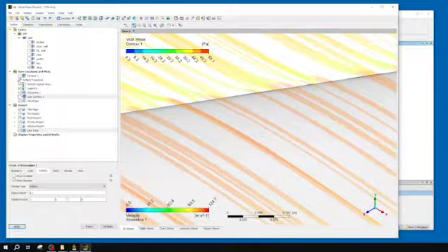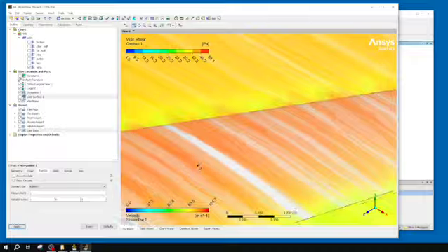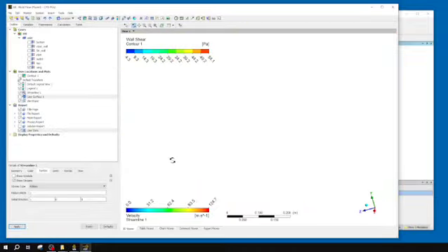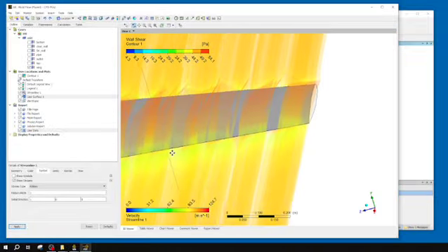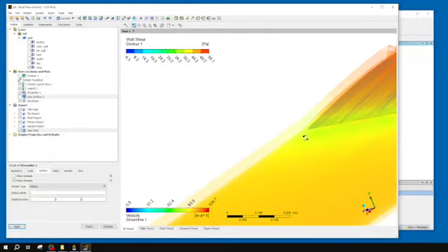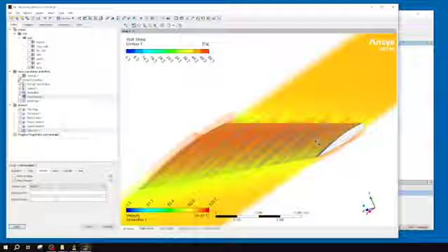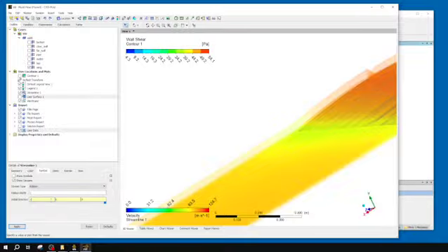But let me give them a 1 scale. How does that look? That's actually quite hard to tell what's going on with 100. But yeah, this initial direction just is a factor to rotate the ribbon. Generally, you probably don't need it, especially for when you're having more streamlines, or if you're keeping your ribbon rather small.